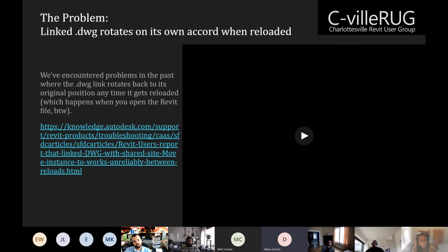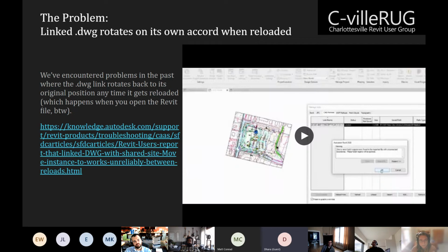So you're just modeling that intersection at the Revit internal origin point, is that all? Yeah, the intersection of the corner of the building. If it's one that you know isn't going to change, then that would be a good one to choose. It can act like the anchor for the project. Anything that moves or stretches about the project, that one point would be constant and not change, and everything else would change around it. Does that help? Yes, thank you. Okay, good.